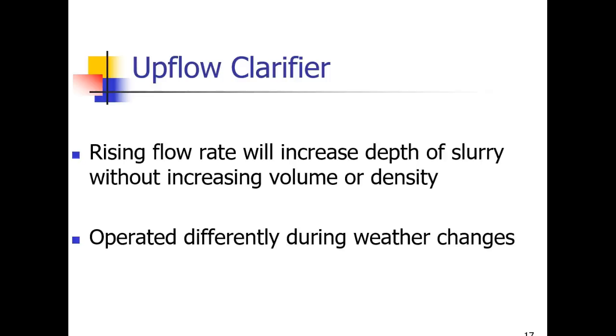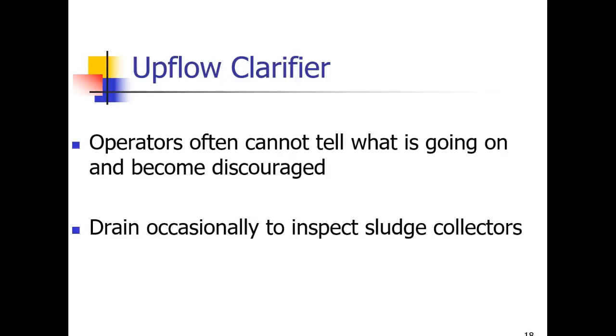Rising flow rates will increase the depth of a slurry without increasing volume or density. They're operated differently during weather changes. And again, the colder the water, the denser it gets. So we have a lot of things that are affected by temperature. Operators often cannot tell what is going on and become discouraged. Okay, again, it's one of those things as an operator, the more you've done it, the better you get. And so again, don't become discouraged, but oftentimes you have to sit there and work with these and tweak them a little bit. You drain them occasionally to inspect the sludge collectors.